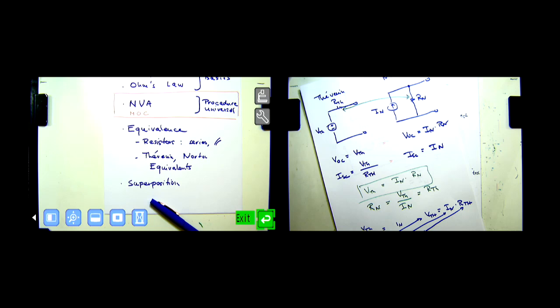Superposition, there are really two things about superposition that are important. One of them, it's an analysis technique. A circuit with tons of sources, 20 voltage sources and 15 current sources or so, we can analyze much more simply if we sort of do divide and conquer. We pick one source at a time and all the other ones we set to 0 and then we pick the next one until we're through. Okay? It's work. But if we behave like a computer, it's just that, right? We can do it at 2 o'clock in the morning if need be. Okay, so it's for analysis.